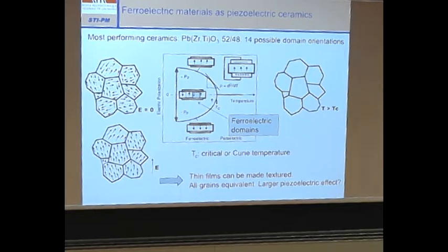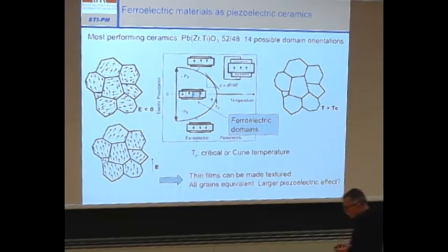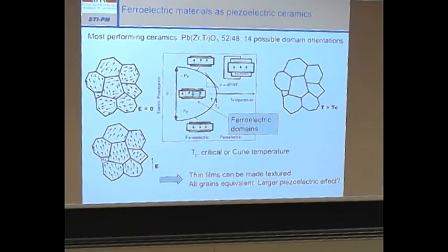And the fact that we have ceramics of PZT and that the ceramic is piezoelectric is due to the fact that we can align the originally random domain pattern with a poling process. Then we can have ferroelectric materials in ceramic form that are piezoelectric after the poling process. With AlN you cannot do that. AlN is not ferroelectric, so you cannot change the polar axis of the crystals. So AlN in ceramics is not piezoelectric. That's a privilege of the ferroelectrics.